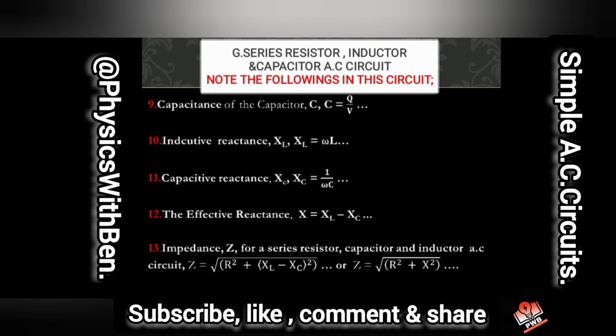This is it here. The effective reactance. Here we talk about reactance. Reactance is the overall opposition to the flow of current offered by an inductor or a capacitor. So reactance comes in when you have, this is the effective reactance, the XL minus the XC. The XL minus XC because the voltage is leading and this is lagging here. And that is why we're having this here.